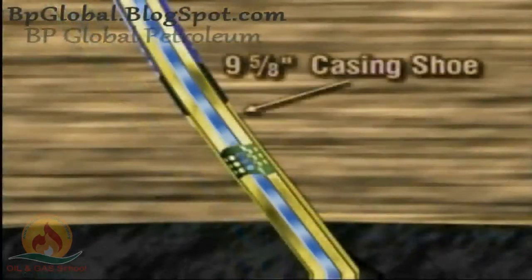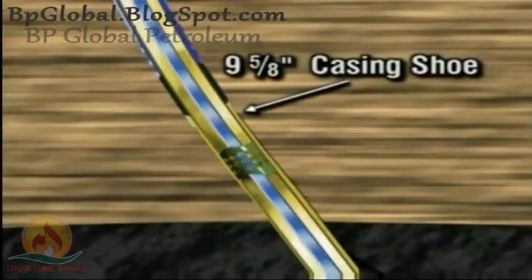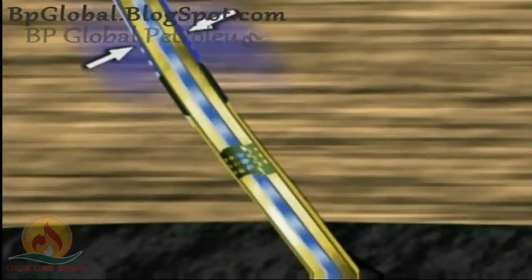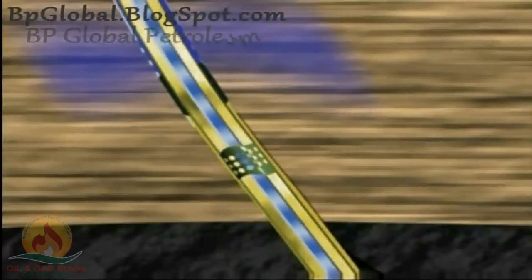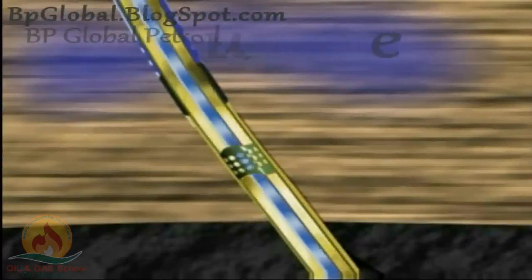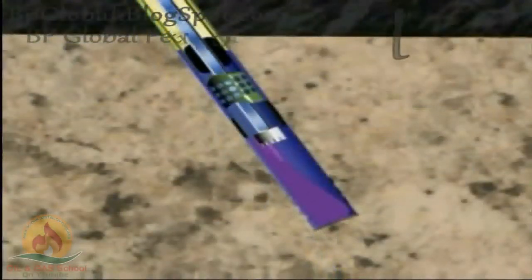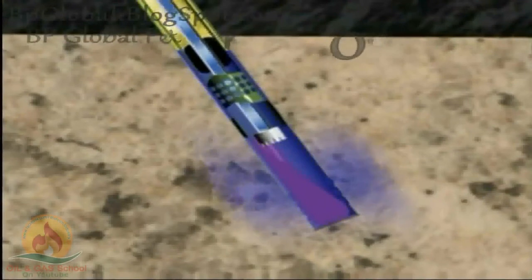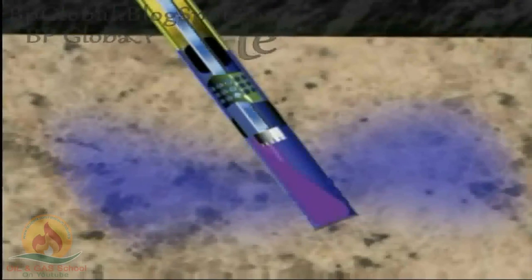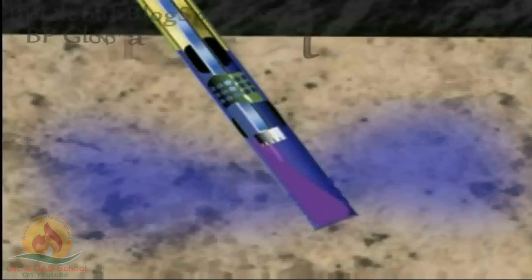If the water injection zone is in a formation above the 9 5/8 casing shoe, then the water is returned to surface, can be pumped back to the outer annulus between the 9 5/8 and 7-inch casings and forced into a suitable water injection zone through perforations at any point in the casing. If above coal seam injection is not feasible, then the ESP can force the water into the zone adjacent to the sump area. This injection system can handle both the produced water generated from its own production as well as produced water from other wells.